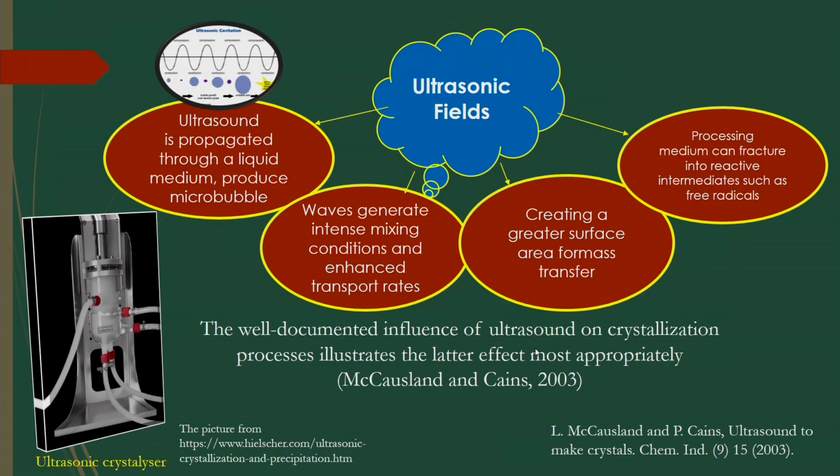So, in that case you have to increase the surface area even for mass transfer, even for reaction, to get reactive mass transfer in an intensified way. You have to produce more surface area. Even in liquid extraction, suppose you want to extract propionic acid from the water into some organic solvent, you have to produce more surface area to transfer this propionic acid from the water to the organic phase.